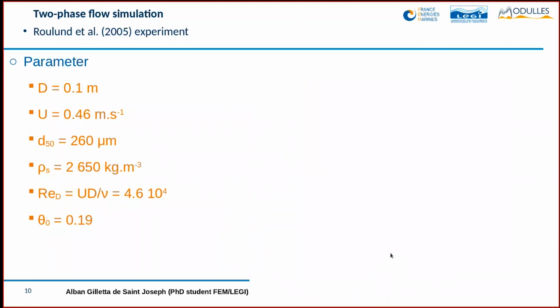In numerical modeling you cannot model large-scale processes. We focus our simulations on small scales, and we are trying to reproduce first some experiments that have been done before about the scour process. Here we are trying to simulate what happens if you put a steady current facing a cylinder.